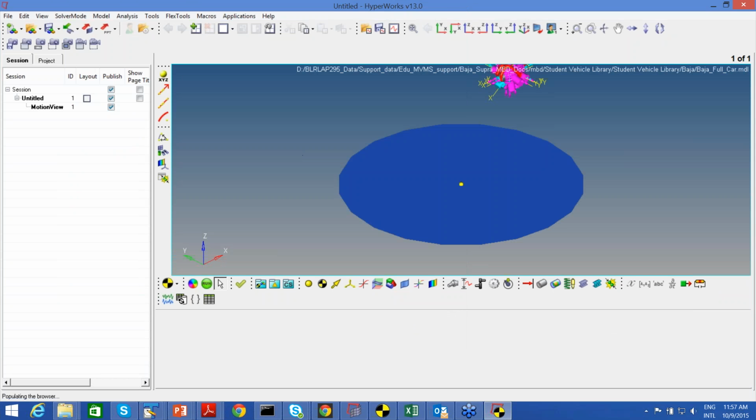but you have to keep that in mind. You should have very accurate input data to design these suspension systems or full vehicle system. Like there are a couple of entities which are very nonlinear. Your spring has a nonlinear behavior. Your bushings have nonlinear behavior.